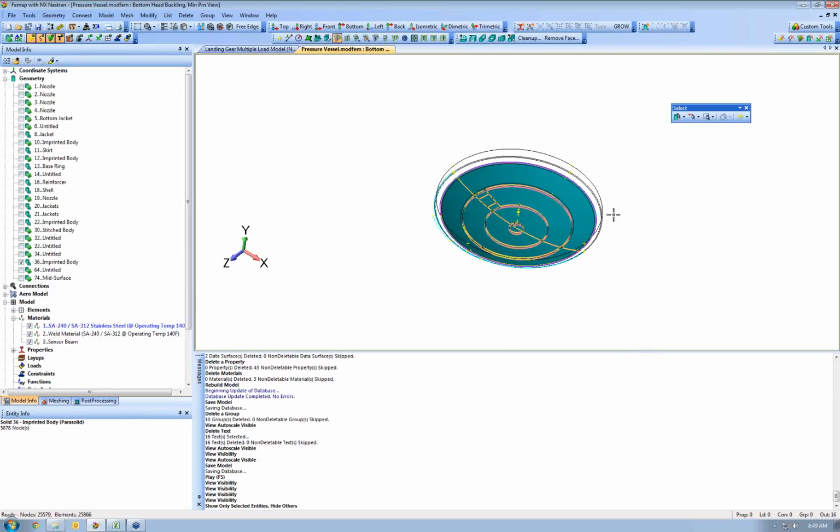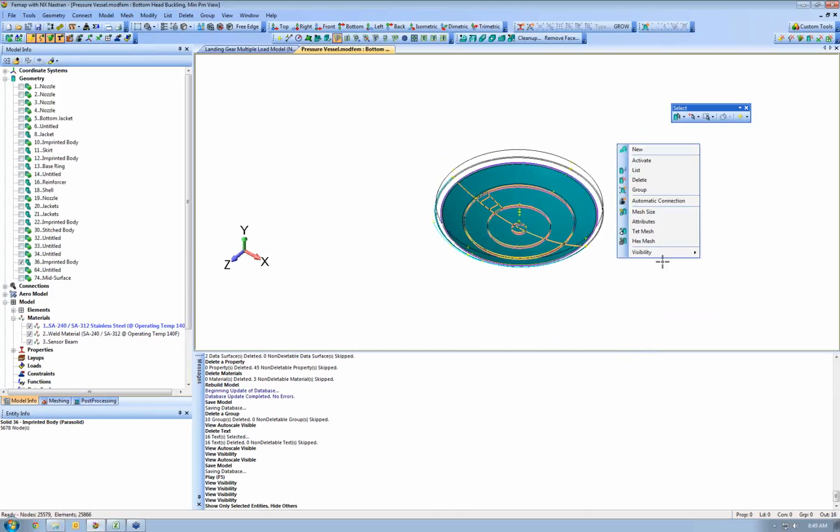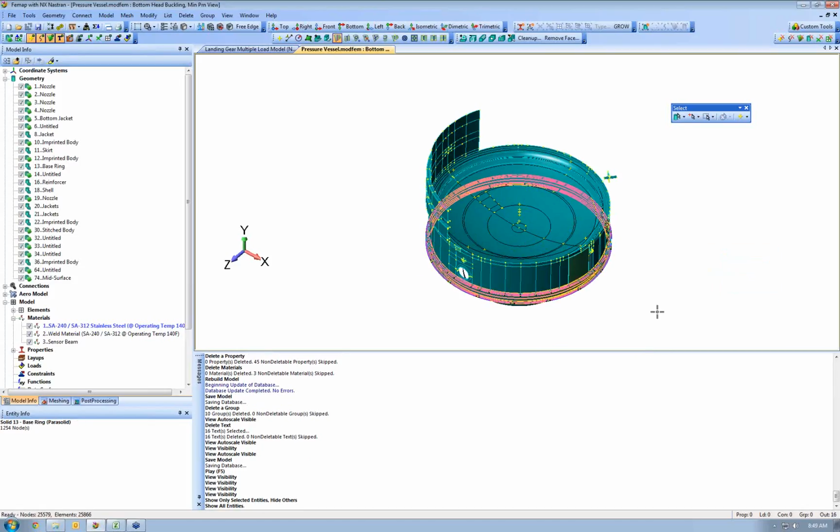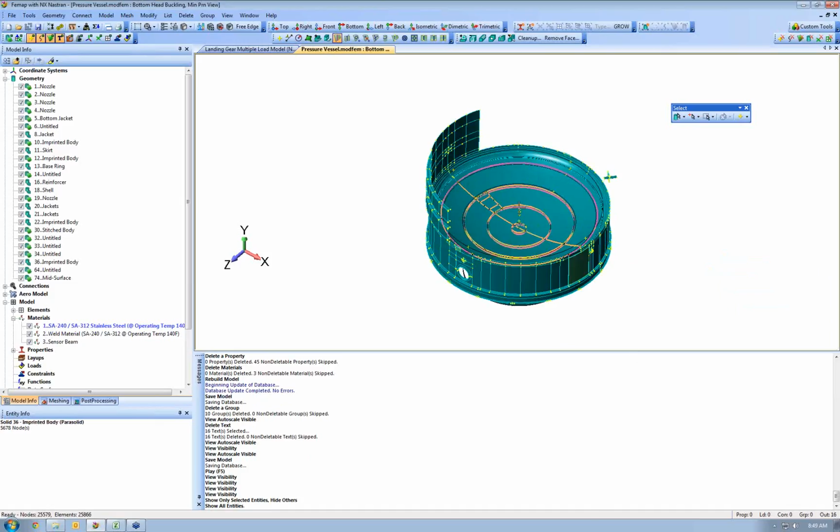I've got a few curves here that aren't associated with any solid, so they're still a part of the view. I can also use this to show all and reset everything. Another trick, it's the same trick but a different way to get to it, is you have three hands, and the shift key, and then right-click. It takes you directly to those visibility options using your selector. So same thing, just one less click. Now this isn't just for solids, this works for any sort of entities you'd like.